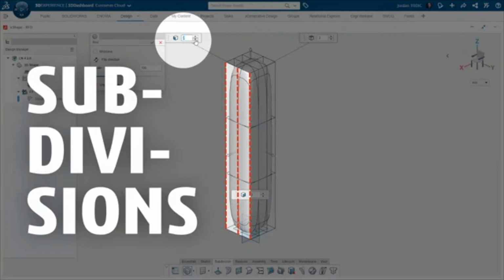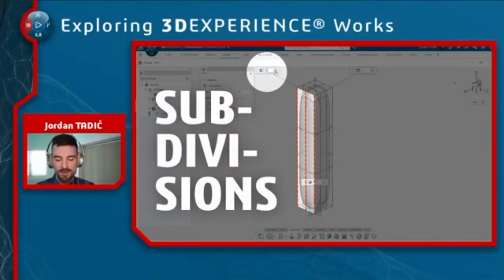The next thing that you're prompted with is why we call this subdivisional modeling. How many subdivisions do you want on the model? So you see those 3 vertical lines going down the length of the model, but in the dialog box that's circled, I've only selected 2. What that represents is the columns of faces that you want along that singular face or side of the model. In this case, I know that I want symmetry down the center of the finger from right to left. So I want to place a line where my symmetry line is eventually going to be, and that's going to make the model update a lot more predictably when I add that.